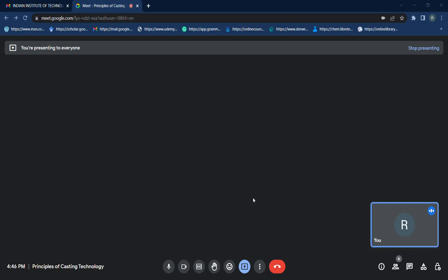Now I will be finding the y part, which is the ratio of the volume of the riser divided by the volume of the casting. So it will come as 0.25 pi d cube divided by the volume of the casting. The volume of the casting is 25 by 25 by 5, so this will come around 3125 centimeter cube. So this will be the y part, and from here you can calculate y as 0.000215 d cube.